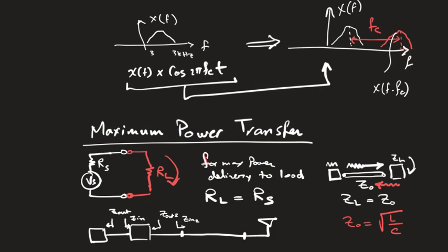It's not ideal. But if you are connecting things that are far from each other, you will still use a transmission line, an RF cable, which is 50 ohm as well, so it will not have to do with matching. It has to do with the fact that these lines are still not ideal. They have some losses inherent in them, okay? Yeah. Any other questions?